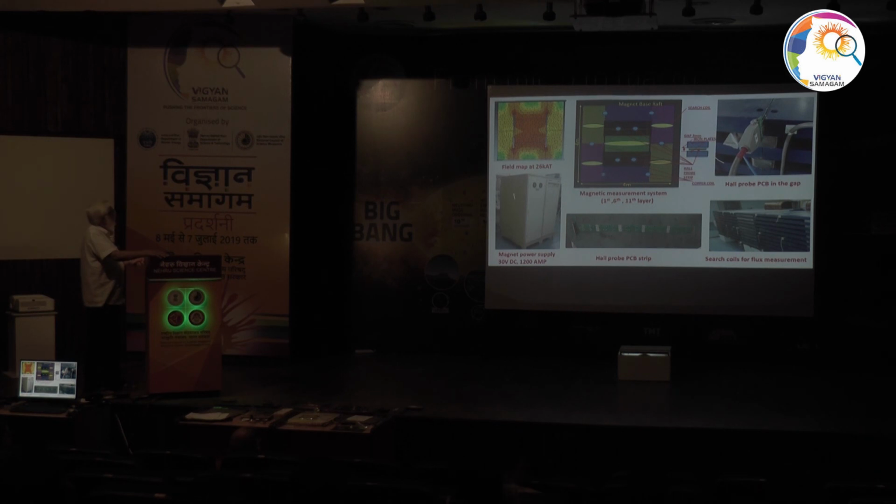This is the power supply. This is an old supply which had one card bad; this was refurbished. And these are the places where you also put coils, pickup coils. So this uses the Faraday effect. If you change the current, you change the magnetic field, you get an EMF, and then you measure that. And so there are 2 alternate ways of measuring it.